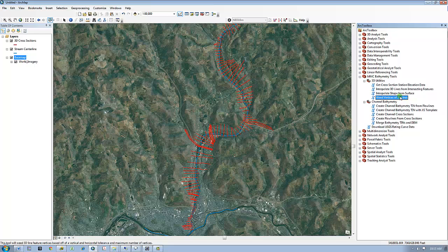This tool would be ideal to use if you have an entire 3D cross-section layer that needs to have vertices of 500 or less per feature. At this point, the user should understand what an acceptable tolerance value is for weeding by testing on different sources.